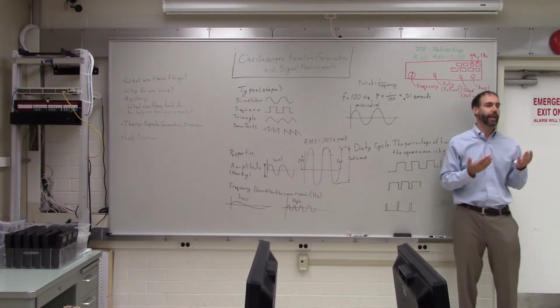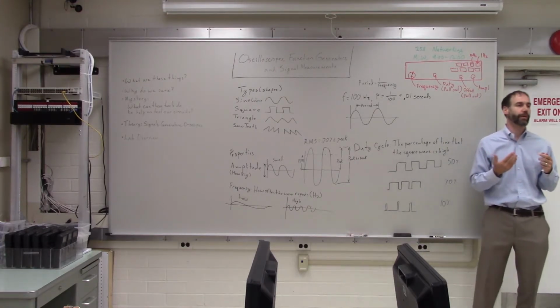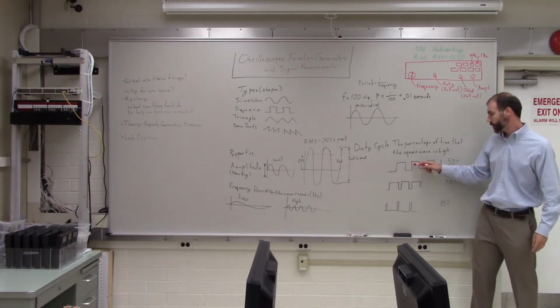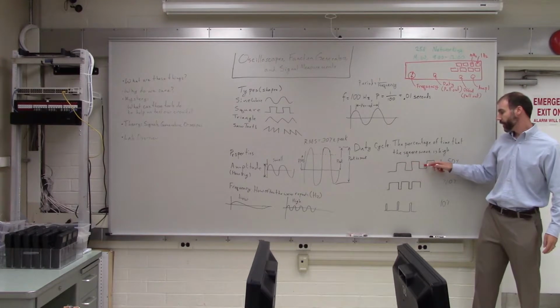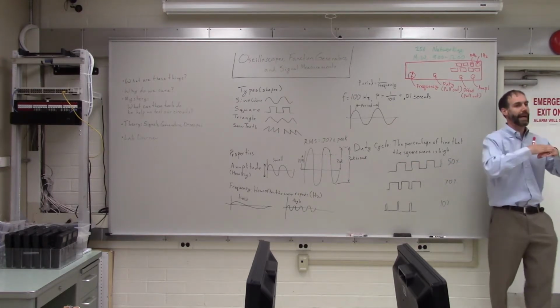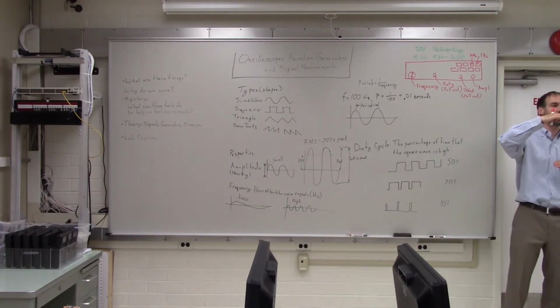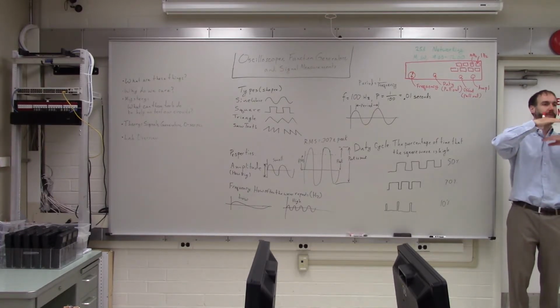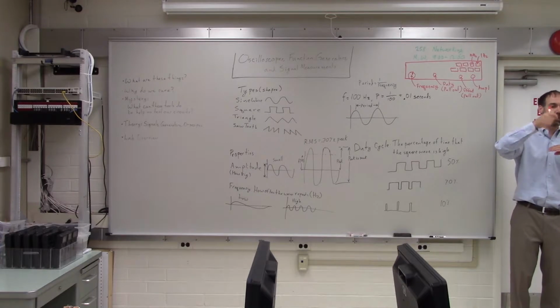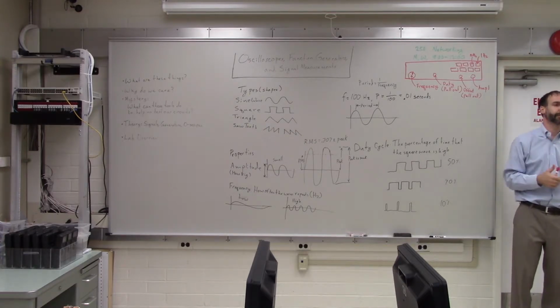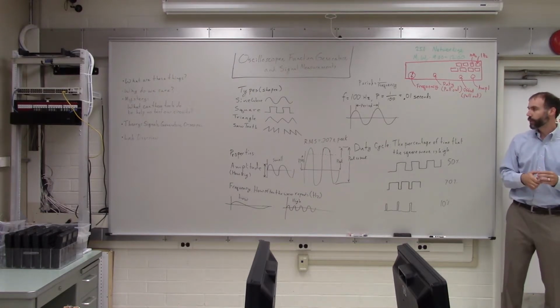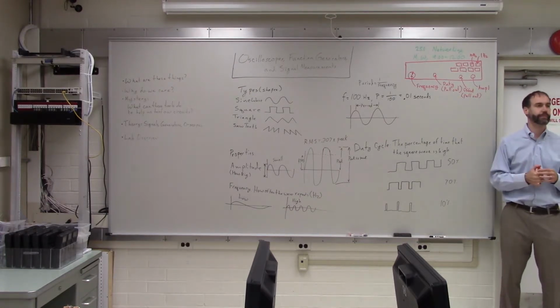If you wanted to replicate something like that with a function generator, if you didn't have the offset knob, you could create a square wave, but it would be centered around 0. So half of the time it would be negative, and the other half of the time it would be positive. So you need the offset knob to pull that up so that the bottom is at 0, and then you can adjust the height to make the top at 5 volts. Okay. So that's one example. There could be other examples as well.